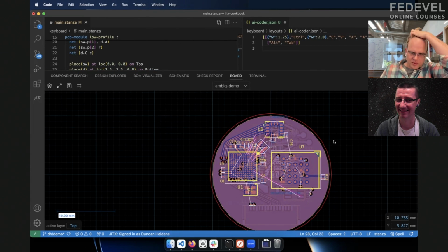I think it's actually a pretty powerful way to create a layout. I do want to add more automation to it though, because we're mostly doing point-to-point routes here. We pick the pin assignment ourselves, and then later try to solve the length matching problem. But it's all a computational problem now, so what we're doing is attaching smarter algorithms for search.